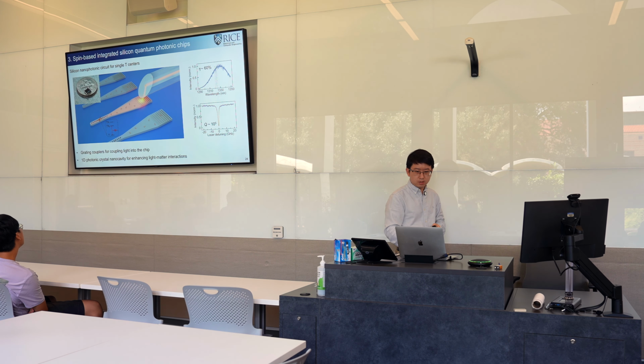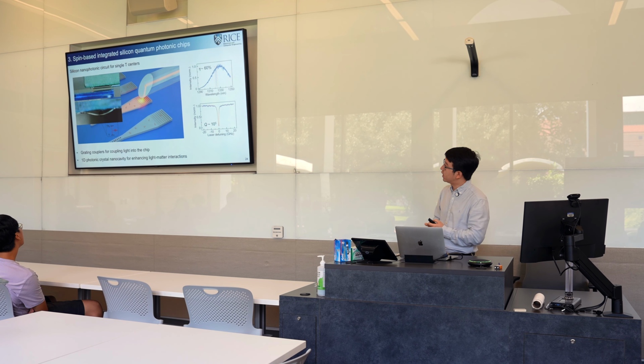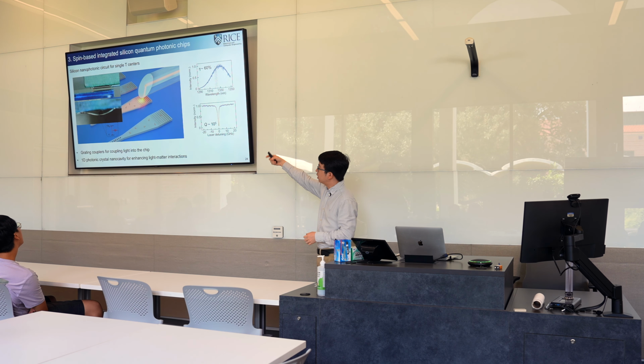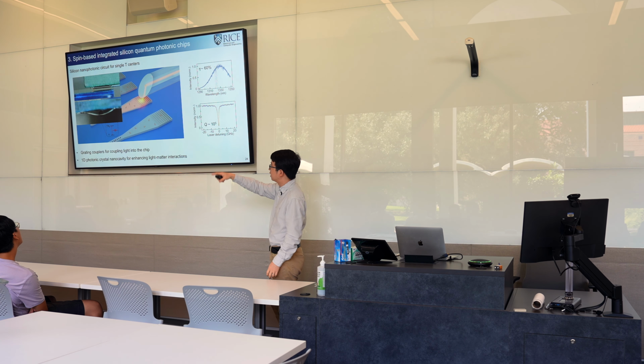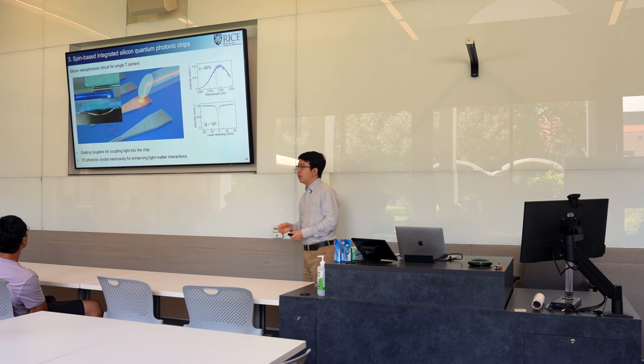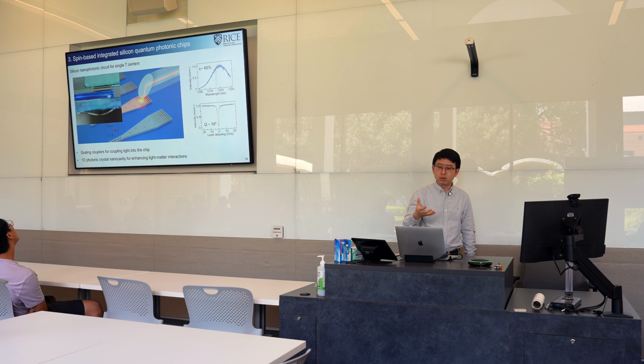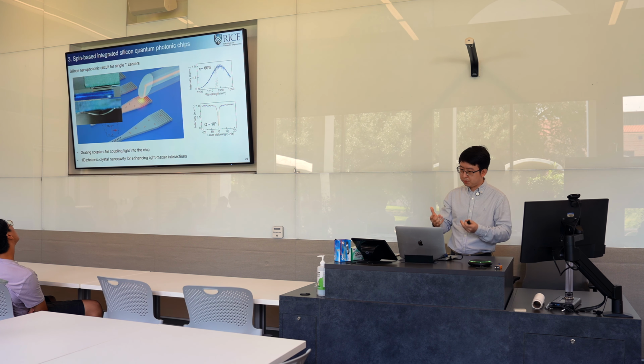We also have microwave devices. So we actually glue the fiber on a PCB, and then on the front end of the PCB, we have a wire bond. So you see that curve. That's a 25 micron diameter gold wire, which we use as an antenna, so we can send microwave into the system to drive the spin transition.